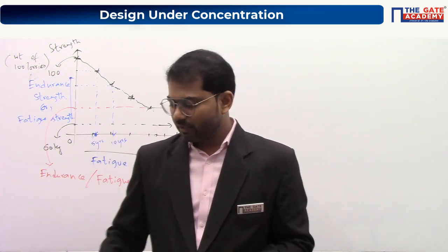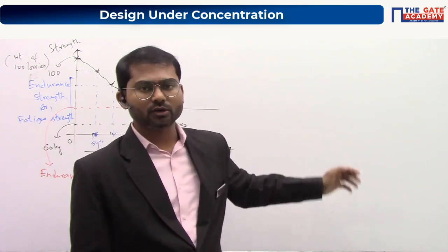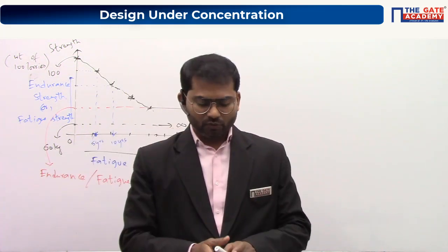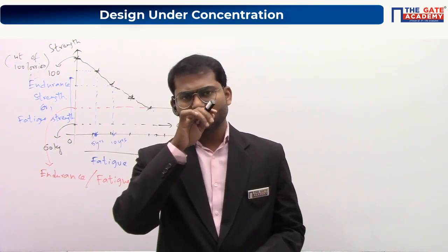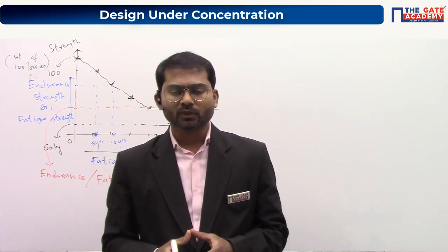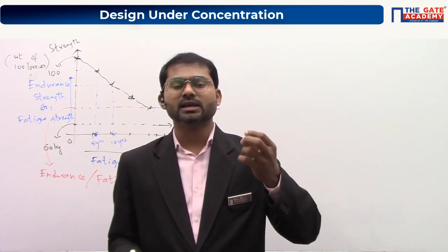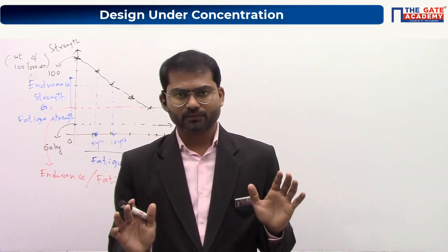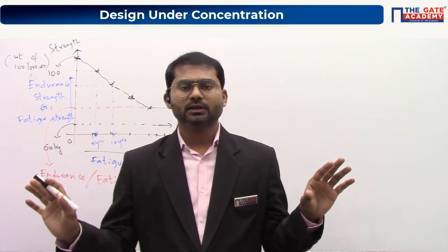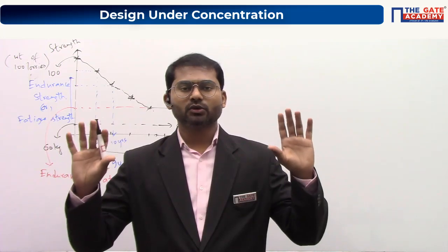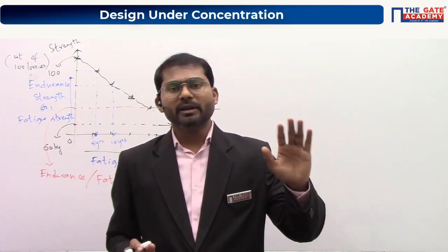So one very important thing, just keep in mind, and I will write down here also. You can copy. Okay. So what I would like to tell you now is this endurance. If you take strength values, basically, whatever the strength values are in static loading cases, that means SYT, SUT, they are experimental values. They don't change with respect to time. Understand? Those are experimental values and they don't change with respect to time. And they depend upon only material.